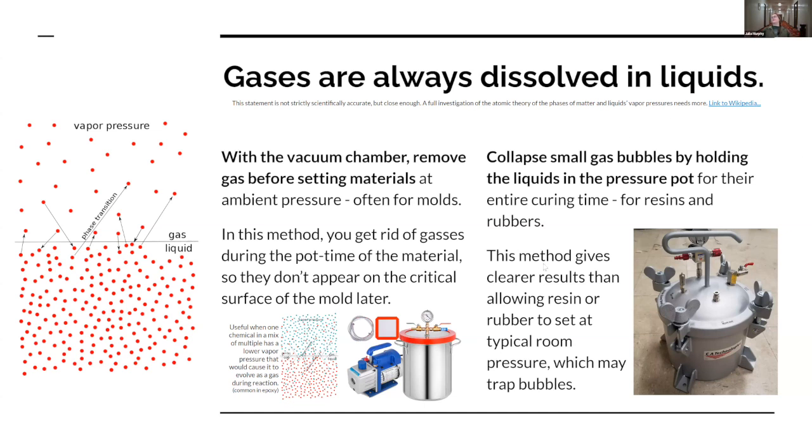I always pressure cast if I can. So this one sucks all the air out. This one squashes all the air down. But in order to keep those bubbles compressed, you've got to let it cure so they can't reinflate.